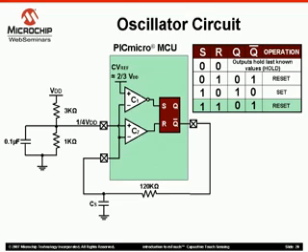latch will be in reset mode, since this latch is reset dominant. More importantly is a condition where both inputs are driven low. What happens in this condition is that the outputs of the latch will hold the last known output values. As you will see, this will become important in the operation of our relaxation oscillator design. Let's step through the operation of this oscillator.